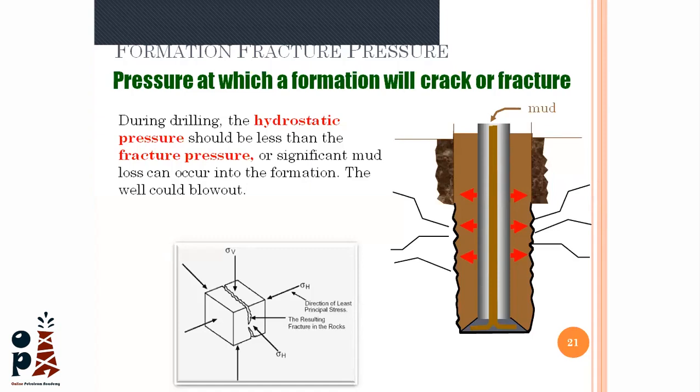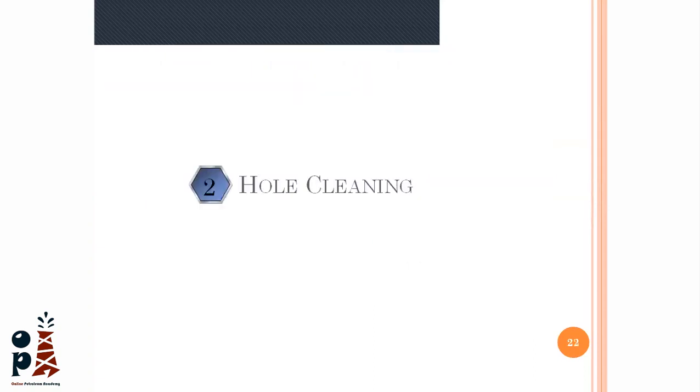The pressure will increase until a point where it starts to decrease. At this turning point, the formation already starts to crack, and this is the LOT, the leak-off test. So this is how we calculate the formation pressure.